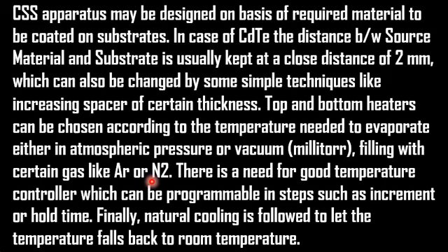The low vapor pressure or low vacuum pressure provides you a diversity in terms of the purity of the deposited film. However, atmospheric pressure has a drawback of causing defects or causing collisions of the evaporating molecules from the precursor material. So they may cause defects in the thin films.